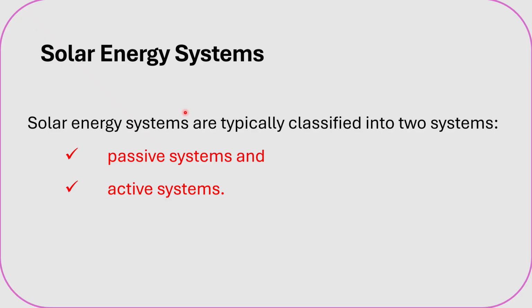Passive systems utilize non-mechanical techniques to control the amount of captured sunlight and distribute this energy into useful forms such as heating, lighting, cooling, and ventilation. These techniques include selecting materials with favorable thermal properties to absorb and retain energy, designing spaces that naturally circulate air to transfer energy, and also referencing the position of a building to the sun to enhance the energy capture.